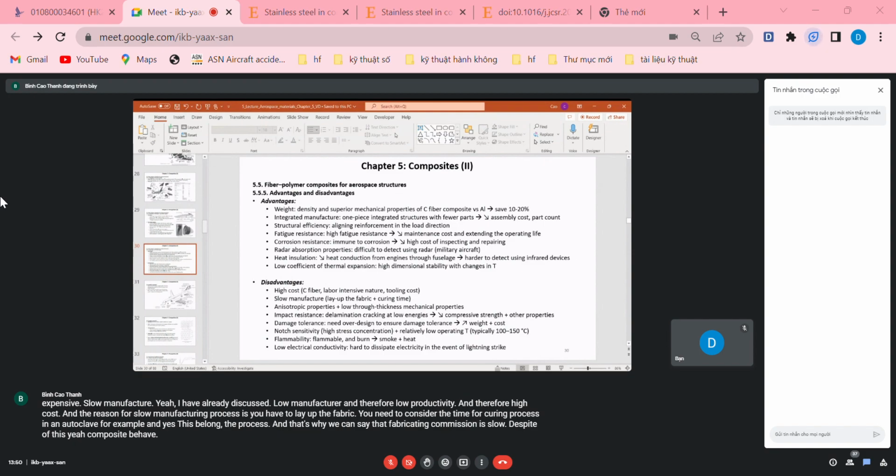Composites also behave anisotropically, because we add, for example, a layer of resin, and next a layer of fiber reinforcement, and other layers. So it is a layer-based approach, and therefore the properties of the material are anisotropic, somehow similar to additive manufacturing, where we fabricate the part additively, and therefore the final material behaves anisotropically.